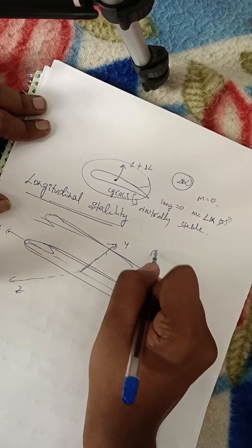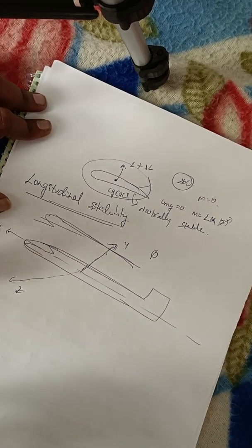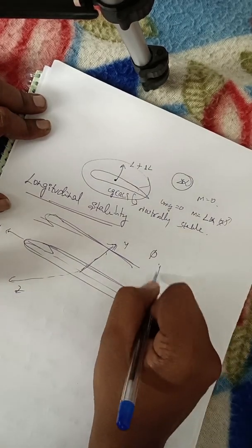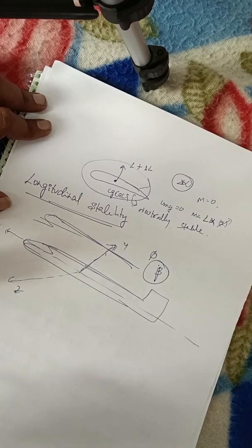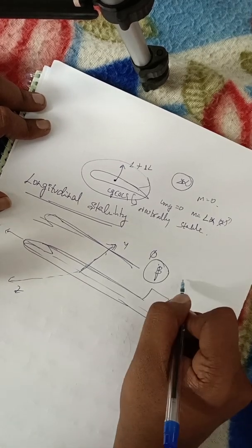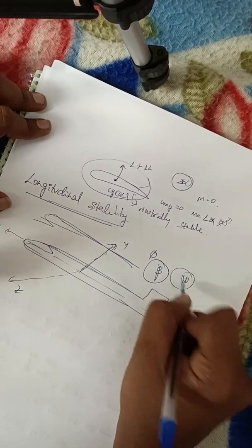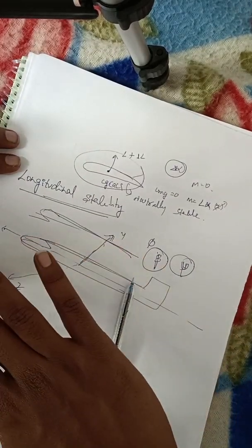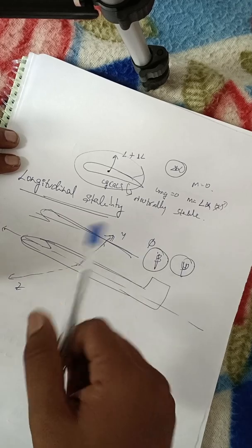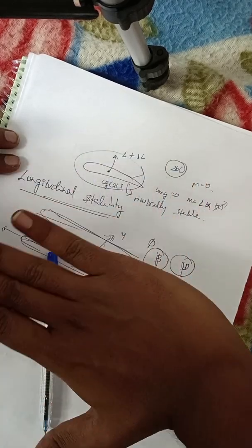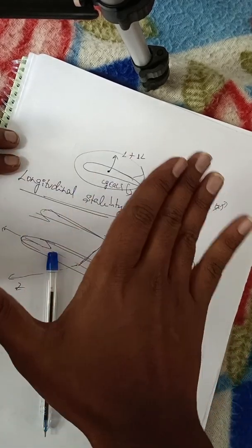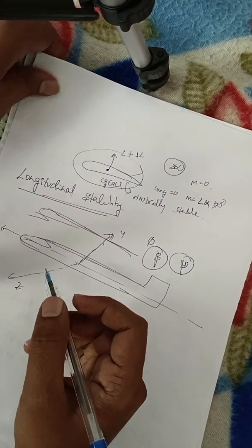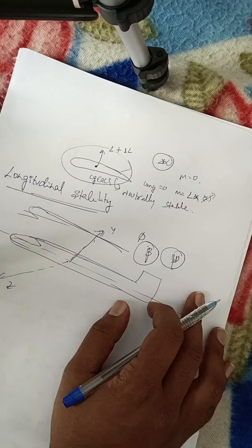There the change is in the bank angle. If I am dealing with beta, the side slip angle, or yaw angle, sometimes we also say yaw angle, both are different, which you will get to know. Yaw angle means rotation about the z axis, the perpendicular axis, like this. If an aircraft moves like this, here you will have directional stability.